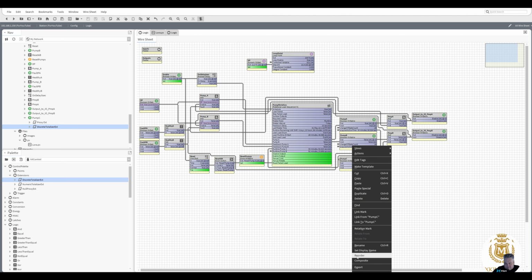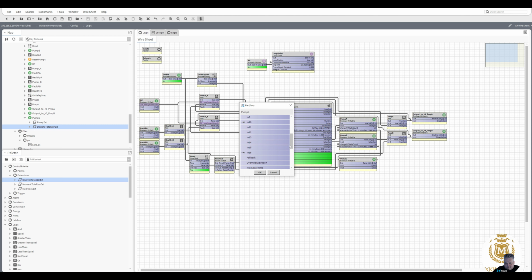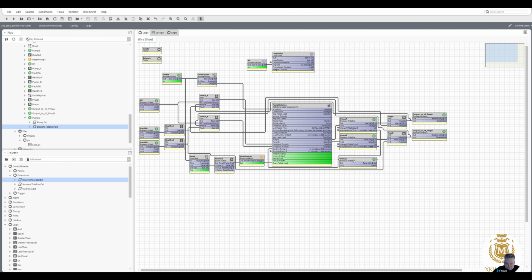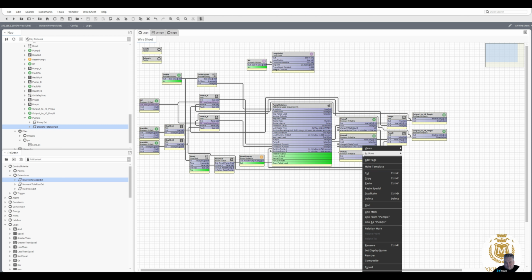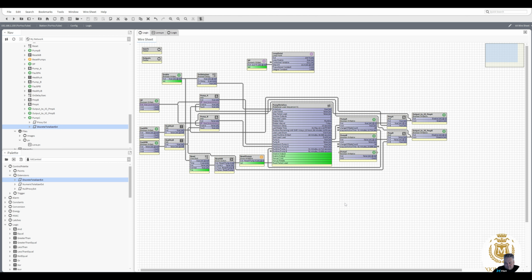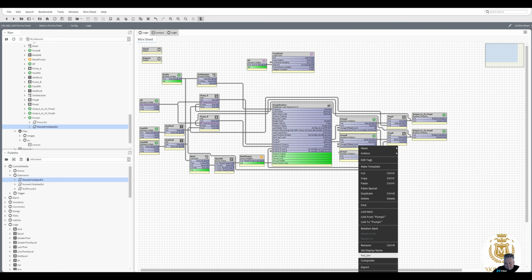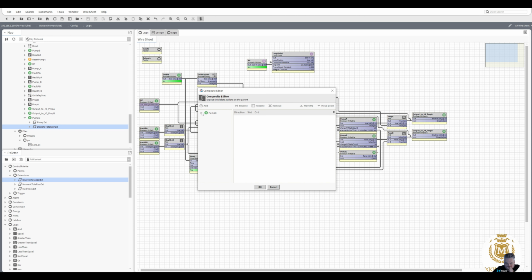I'm just going to tidy up this and take that in 16. You don't have to do that, it's just my preference. I just like to keep things nice and tidy. So sorry, I never told you. I'm pressing composite there now. So I'm right clicking the pump C, going down to composite, expanded pump C, expanded discrete totalizer, moving that slightly across, and I'm going to go for the change of state count, so how many times it stopped and started, and elapsed time.